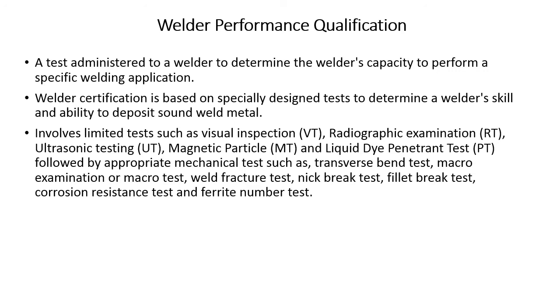And it just depends on what your requirements are and what you're qualifying the welder to do. Not every welder needs all of these tests every time. Certain military applications, Navy nuclear or whatever, might be more stringent than something that's welding handrails on a specific platform or something to that effect, depending on what your code requirements are, your customer requirements and specifications.